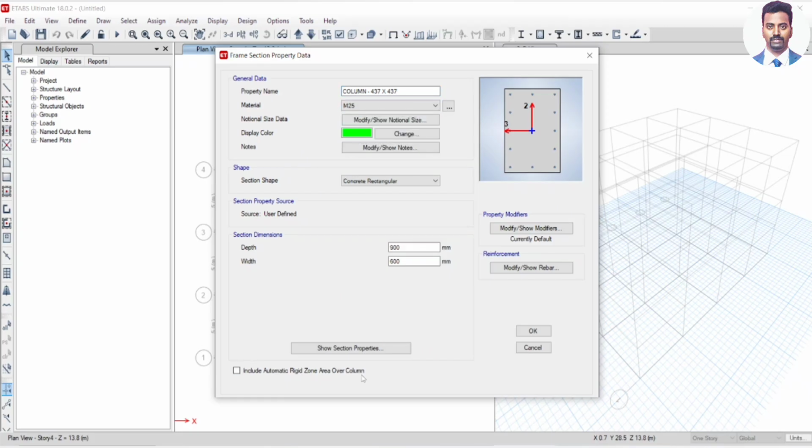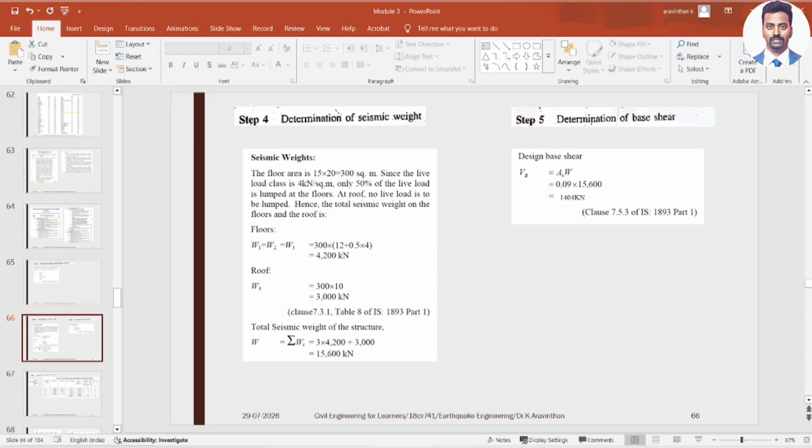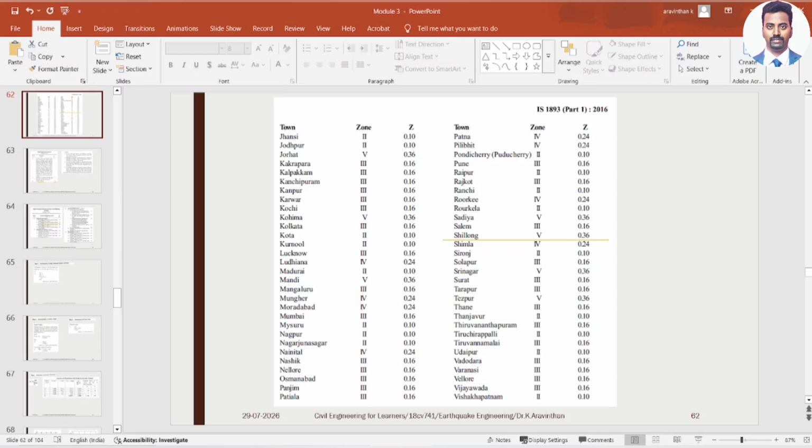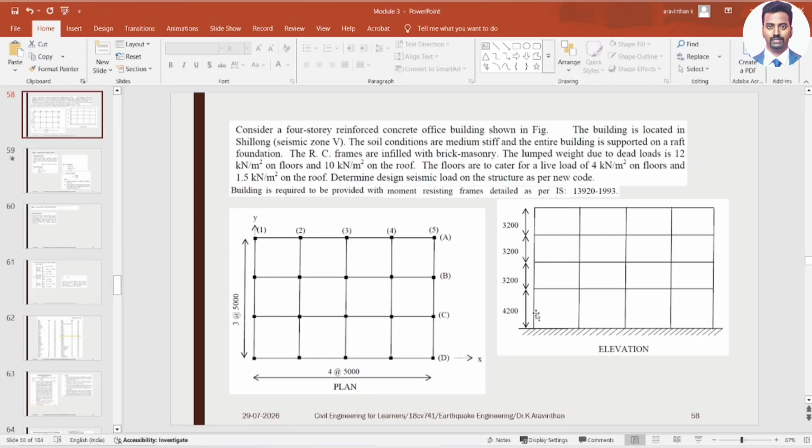Here in this problem they have not mentioned any K value. K is called stiffness. So stiffness depends on the member properties. Here it is not mentioned as K in different form. You can take stiffness for each and every floor as same. K1, K1, K1, K1. There is no K2 or K3 because the column has the same size, and every material property is same for beam and the column. So if you match with that, you will be getting a structure which has even stiffness.